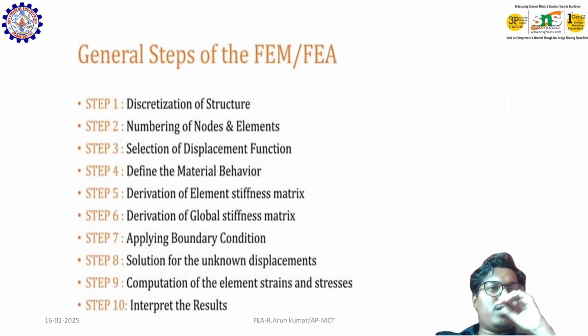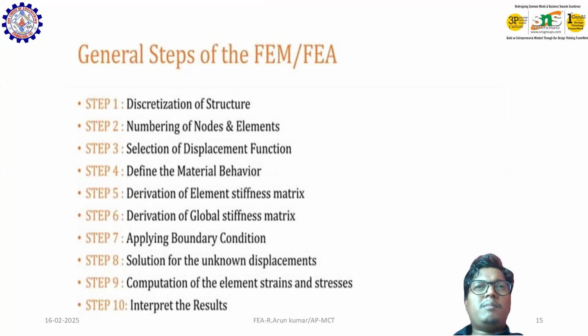Similarly, you do the same for other cases. For example, if I fix the third node, you have to eliminate the third row and third column of the stiffness matrix, and correspondingly cut the force matrix. Once you substitute all the data in the general matrix, then only do you substitute the boundary condition. So it is easy that way.